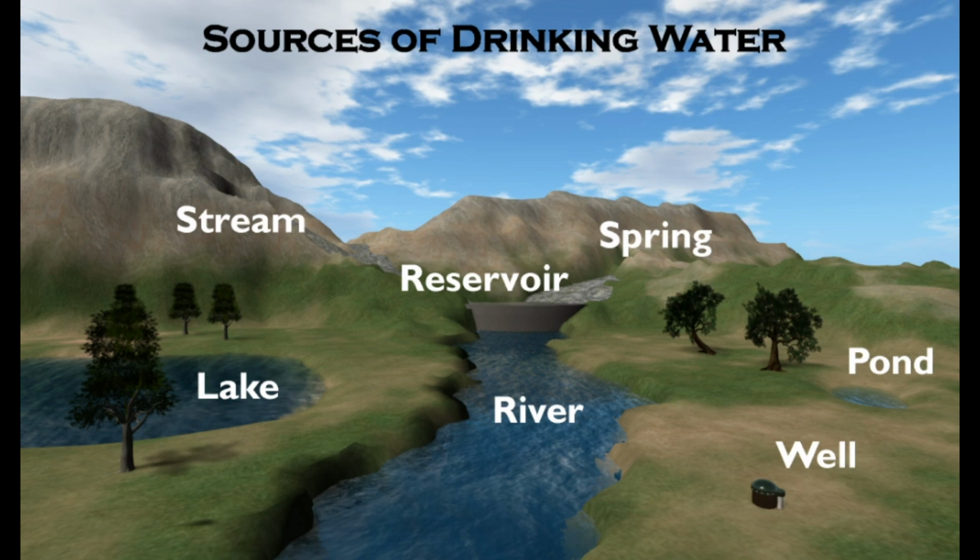Surface water: streams, rivers and lakes are the major sources of surface water. Usually these sources fulfill the requirement of municipal supplies. Water in these sources originates partly from groundwater outflow and partly from rainwater which flows over the terrestrial areas into the surface water bodies. Outflows from groundwater bring in dissolved solids. The surface runoff contributes turbidity, organic matter and pathogenic organisms.